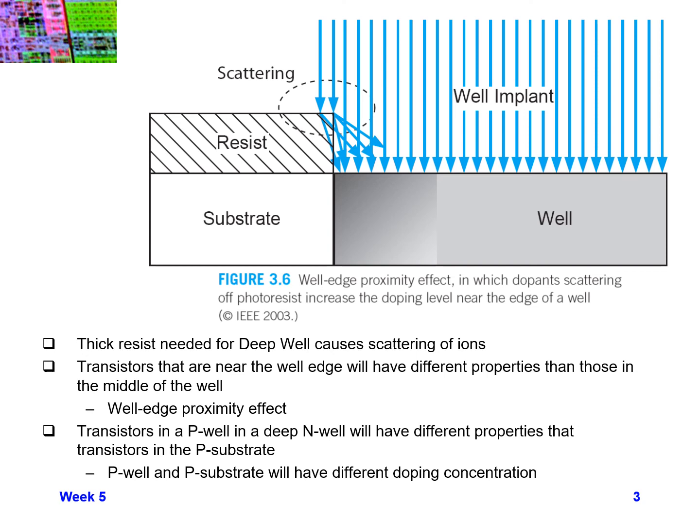You have to make sure that you model transistors that are in the P well differently, either with different threshold voltage or whatever the properties are that are different on that transistor, than transistors that are inside a P well that's inside the deep N well.